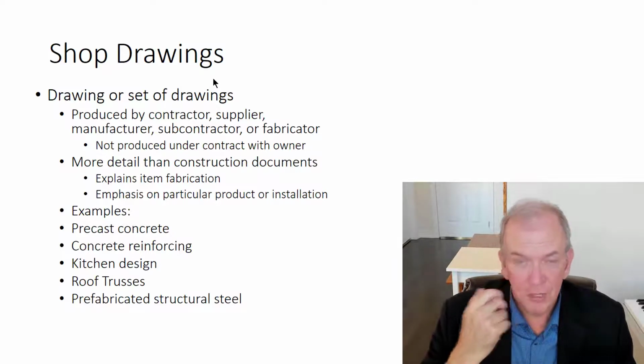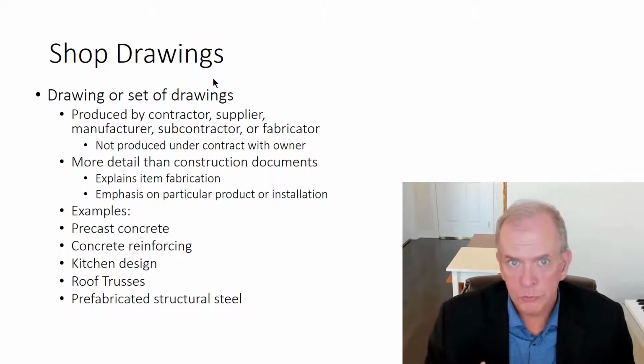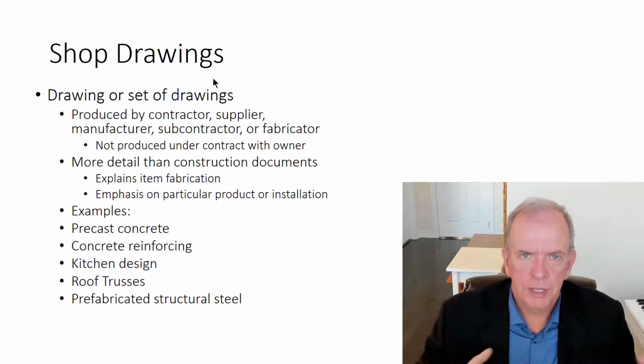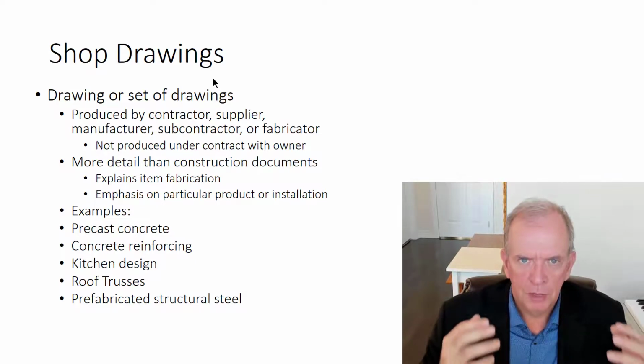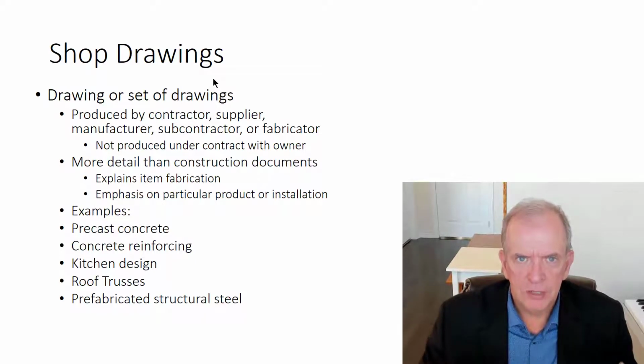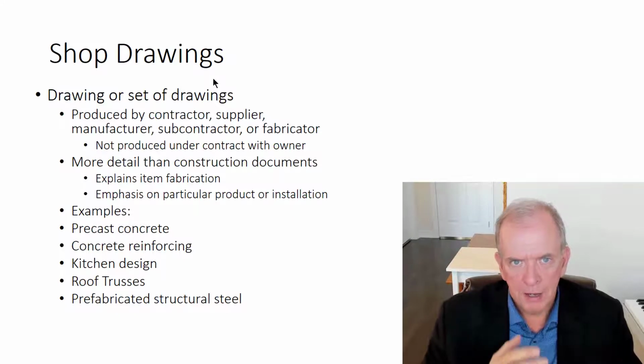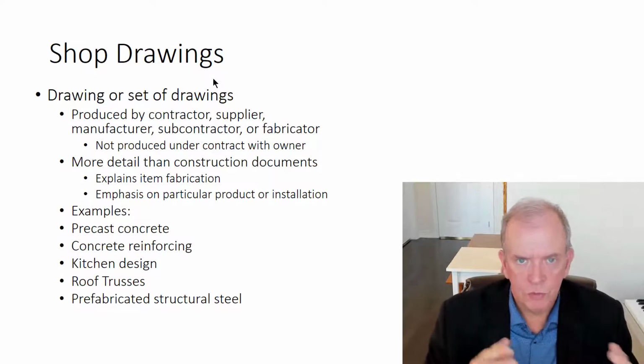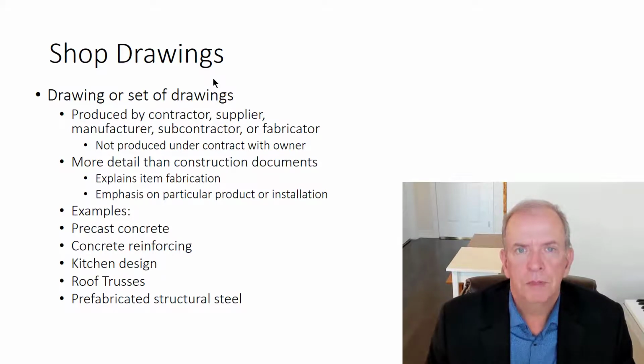Otherwise, you get it very confused and you wouldn't know which rebar goes where. So they try to make it very easy for the actual laborers installing the rebar to infer that information and then install it properly. But they better have taken the information from the structural engineer and done it right. And the structural engineer, before it goes into place, wants to review it and make sure there's not been some error or something of that nature. So that saves a lot of trouble in the construction process later on.